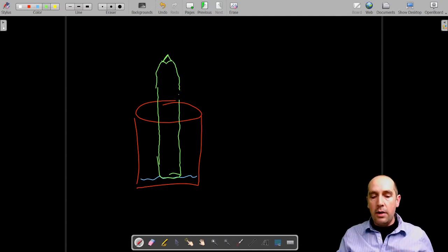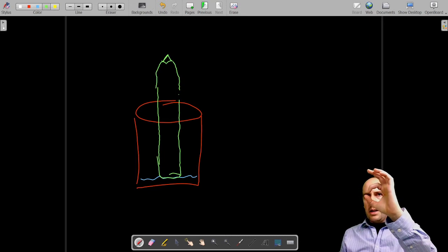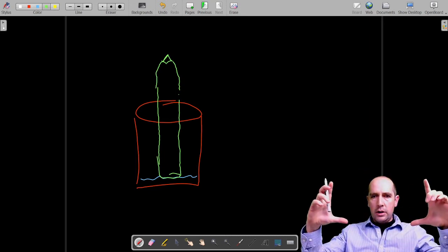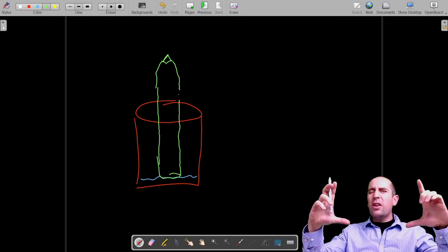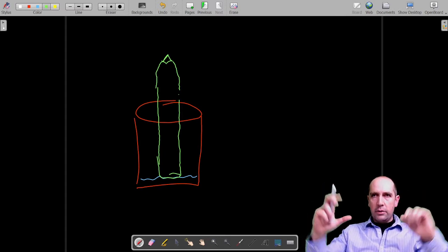You really have large pieces of material that can be completely defect-free or almost completely defect-free. So these ingots can be grown in several different sizes. Typical diameters go from around 1 inch, so about 25 millimeters, to about 100 millimeters, or 300 millimeters for the largest ones. So 300 millimeters is about that big.